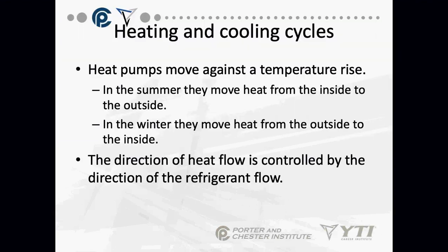Again, we're moving against a temperature rise. In the summer, they move the heat from the inside to the outside. In the winter, they move the heat from the outside to the inside. The direction of heat flow is controlled by the direction of refrigerant flow. Let me say that again.